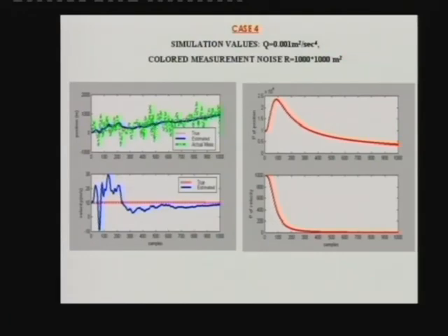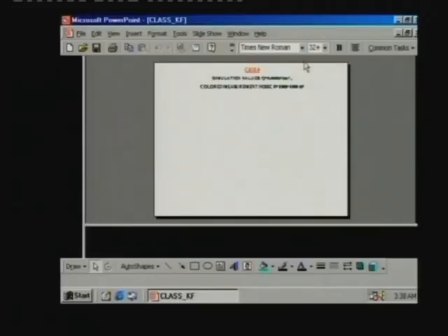So this is why in this case you should actually add the noise states also to the Kalman filter, extend the states and then reformulate the problem such that the noise states will also be estimated, then your actual system state estimation will become white and flat again. Okay. So again convergence is still slow because our R is still very high. So this is what I wanted to show about Kalman filter. You can yourself do many experiments with your own code and see better things.